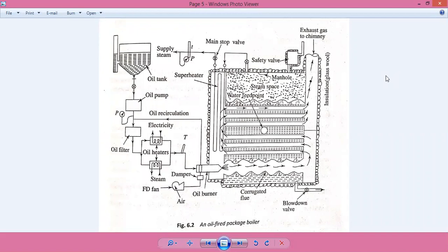So the most important part in using is the higher pressure, it is limited by the thickness of the shell. The higher the pressure, the higher will be the thickness, and you have to make the drums with higher thickness steel parts, which means it costs you more. So high pressure needs thick shells, and the thicker the shell, the higher will be the cost itself.